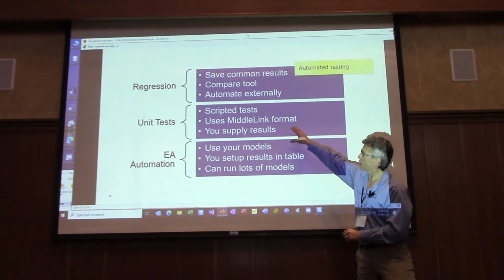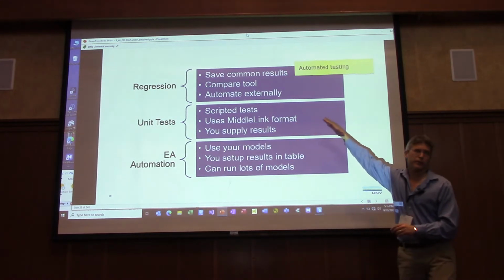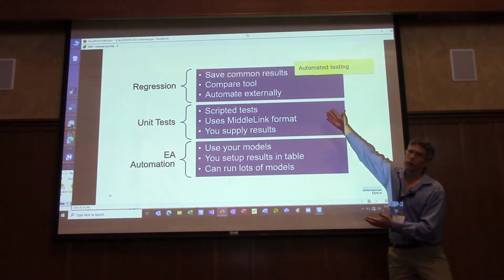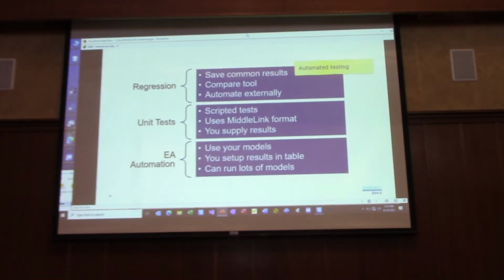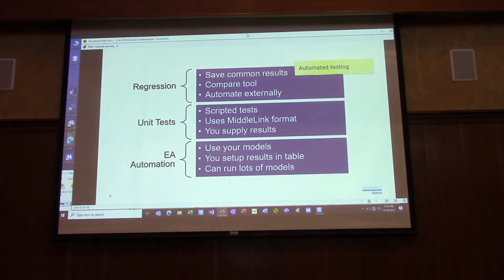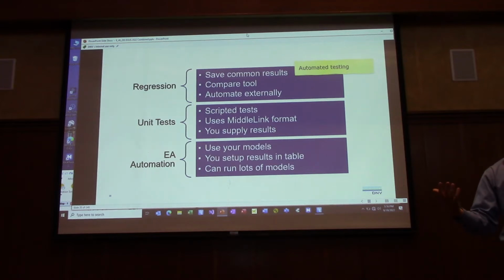Some new work on an old system are unit tests. Now you can use all of this stuff, and we built it so that you can use it. Why would you want to use a regression? You can use that for your model build process. So if you've got models coming out of GIS and you want to see what the differences are between this model and that, you can compare databases, but what we're interested in is, I don't care so much if the data has changed. What I want to know is, have my results changed? Are my fault levels different? Are my voltages different? So that's what the regression could be used for.